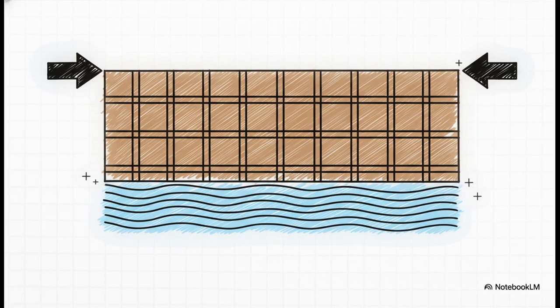But here's the catch. To make those elegant equations actually work, engineers have to assume 7 perfect world rules. They have to assume the aquifer extends infinitely, that the soil is perfectly uniform everywhere, the initial water table is flawlessly horizontal, and that the water flow remains totally smooth and purely laminar. It's a mathematically perfect scenario that gives them a solid baseline to work from.